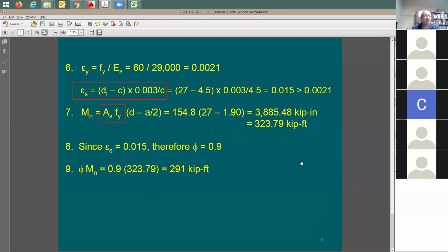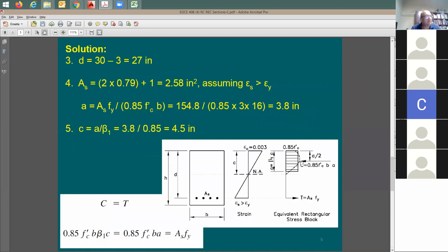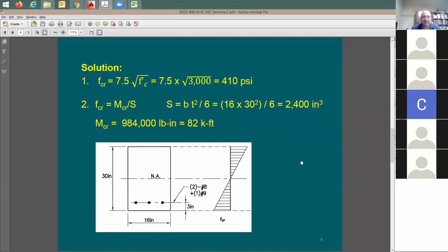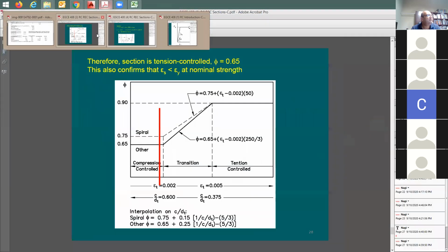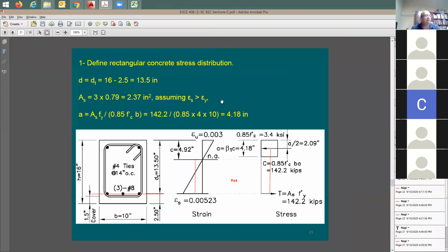So if your design is kind of tight and you'd like to reduce the rebars on the bottom, what you can do here is to add a little bit of the compression reinforcement effect, because the top reinforcing, you need to have it anyways. You cannot have a beam without the compression reinforcement. Let me go there. Look at the beam. You need to have some rebars here on the top. You cannot build the beam without having top rebars. Otherwise, what are you going to be hooking these ties to? It's going to be loose on the top once you put concrete. I mean, it's not going to be doing any work here, but you need the ties. We're going to be talking about the use of ties later on.